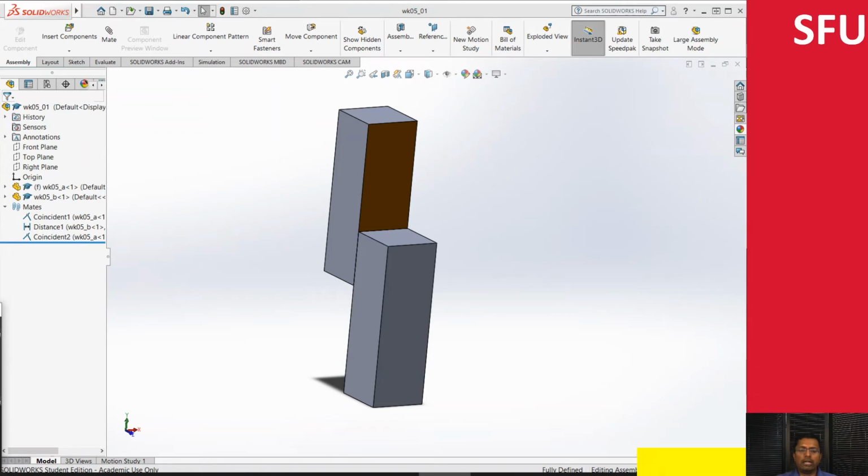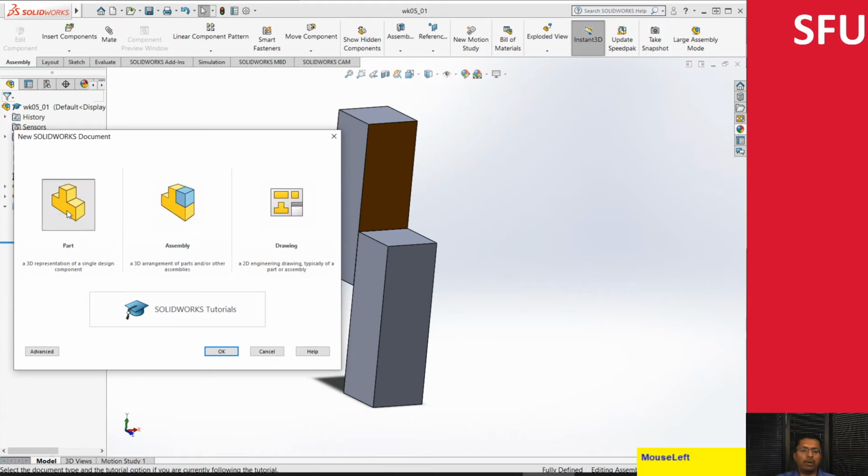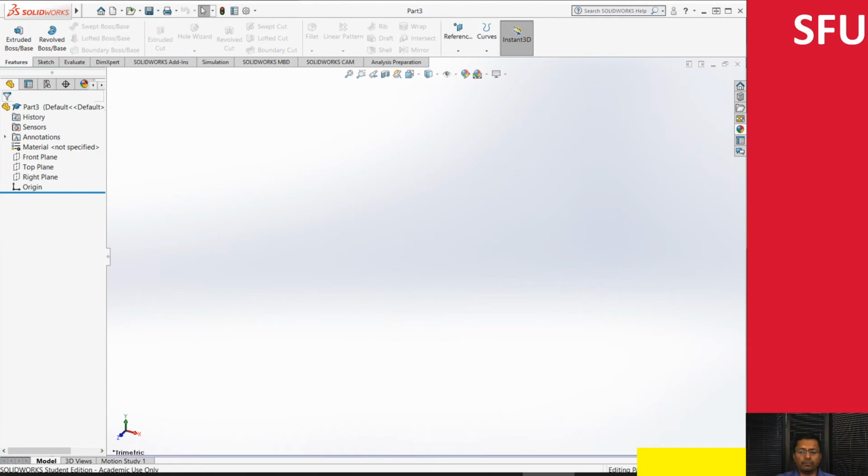So let's look at our table assembly. We have two parts which we can use as our legs. What we need to do is create a part which we can use as the top of the table. For that, I'm just going to do Control N, click on part, and because I made a mistake in setting up the units, I'm going to change this to millimeters over here.